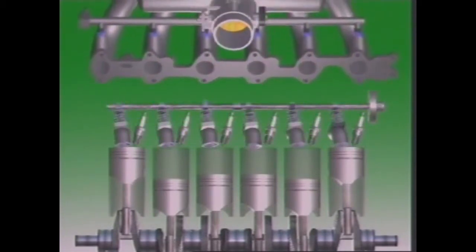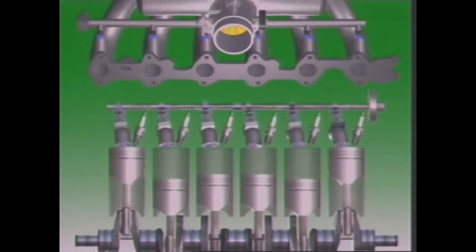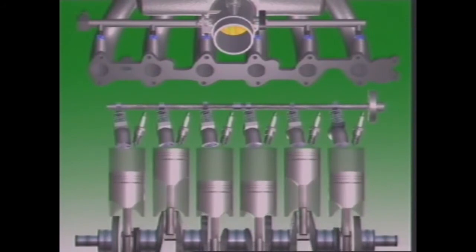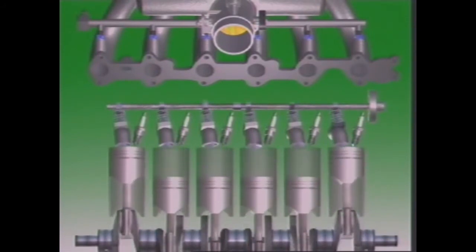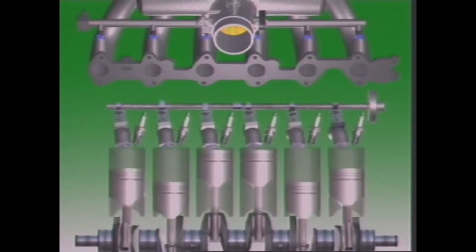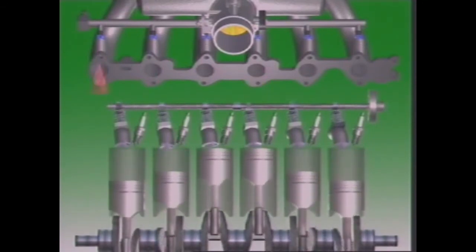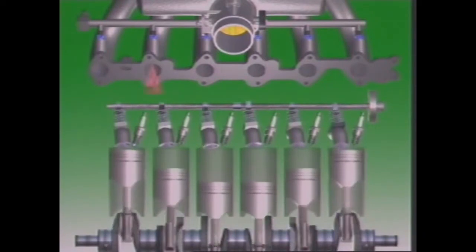Some sequential systems use a pre-injection of fuel. This means all injectors open simultaneously to provide an initial injection of fuel. This happens only during cold cranking, and there is a time delay to prevent pre-injection occurring again within a certain time if the engine does not start. The system reverts to sequential injection when the engine starts.